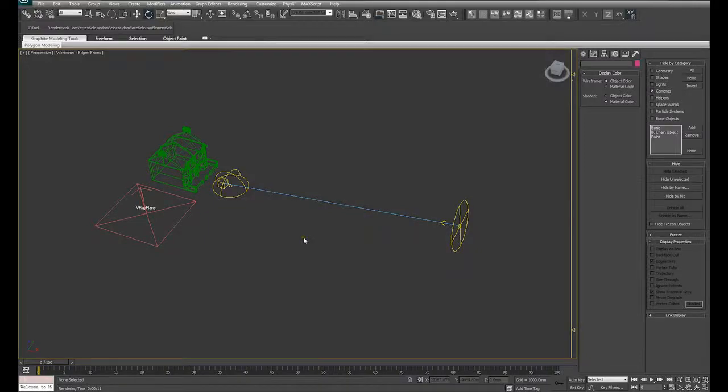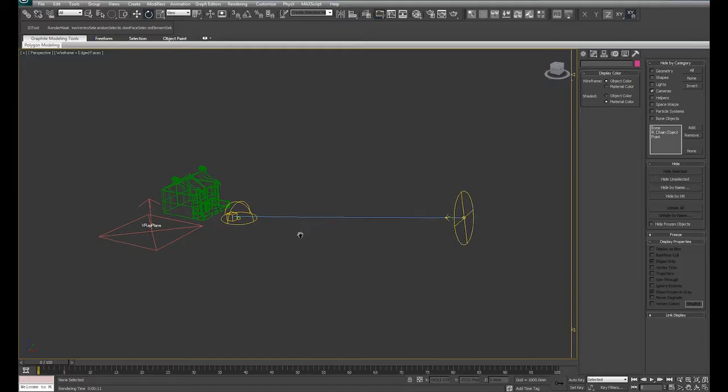Okay, this is a tutorial covering lighting in V-Ray using an HDRI sky dome and VraySun. I've got a basic test scene here to indicate what we're looking to achieve. Effectively, we want to light our scene using an HDRI via this V-Ray dome light. The benefits of using HDRI are that it'll give you a very realistic, very natural, varied quality of light on your scene, and it'll also give you accurate reflections.